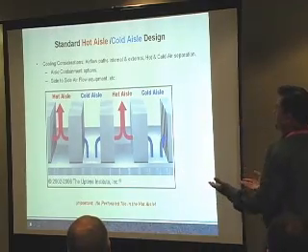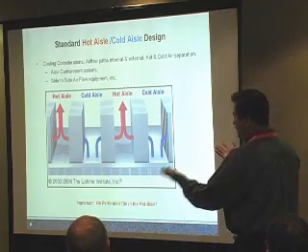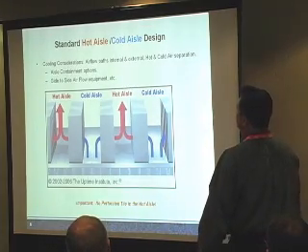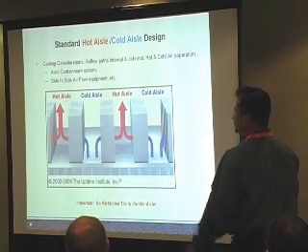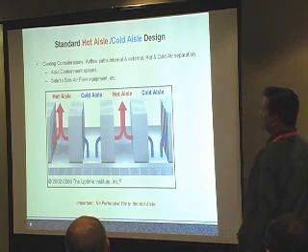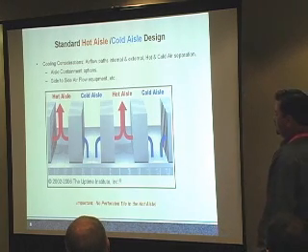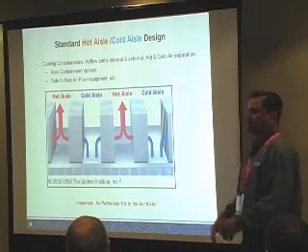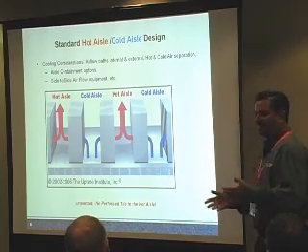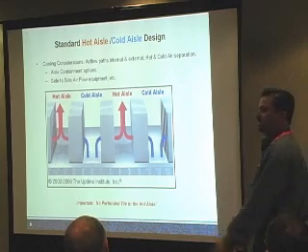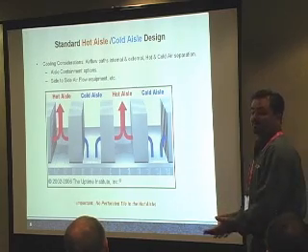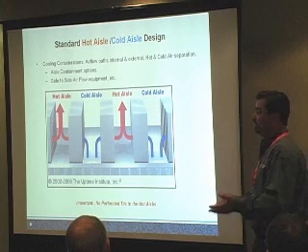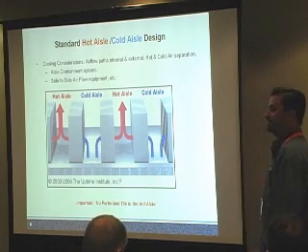But looking at standard hot aisle, cold aisle designs, everyone's seen this shot. Pretty common sense thing. Most important thing was the bottom part in red. All right. No perf tiles in a hot aisle. Everyone thinks, oh, I've got a data center and I'm walking through, oh, this place is hot, I better start putting tiles in it. You're wasting money right there. So if you have a perf tile in the hot aisle, get it out.